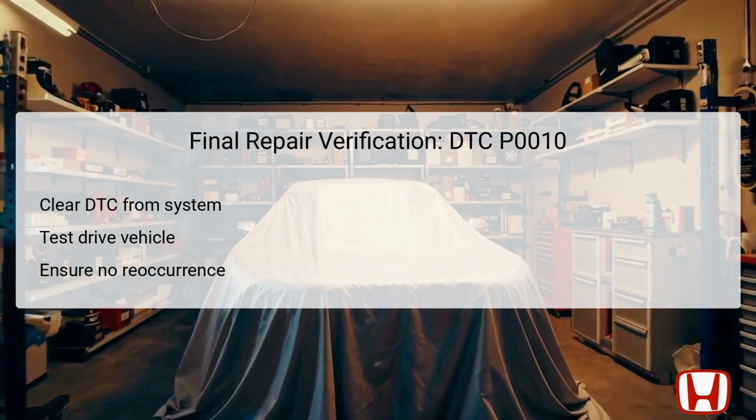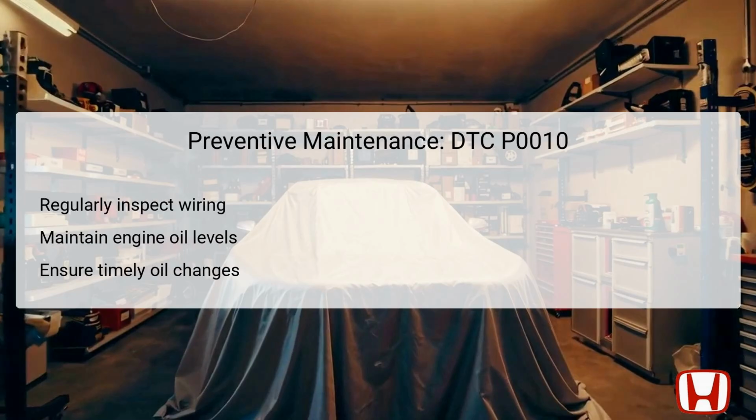successfully rectified the issue. Preventive maintenance plays a crucial role in avoiding issues like DTC P0010 in the future. Regular inspections of the VTC wiring and connector are essential, as they can prevent corrosion or damage that may lead to circuit issues. Additionally, maintaining proper engine oil levels is vital because the variable valve timing system relies on adequate oil pressure to function efficiently.